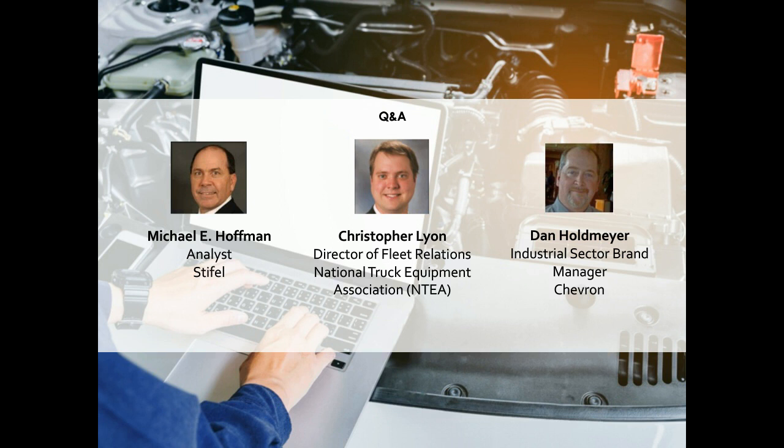So much so that it resulted in cavitation and even some drop off in oil pressure in the system. And if we were allowed to go further, all that dirt and debris floating through those hydraulic systems, particularly on the hoses, can abrade the inside of those hoses, causes leakage, and causes problems that way. So I guess the short answer to that is no, you cannot rely on it coming out of the drum to be as clean as it needs to be, and there are ways to clean it up before it goes in there, or buying cleaner oil in different forms and putting it in there, but then you have to maintain the cleanliness too once you get it in there. Thank you for the question. That's a good one.